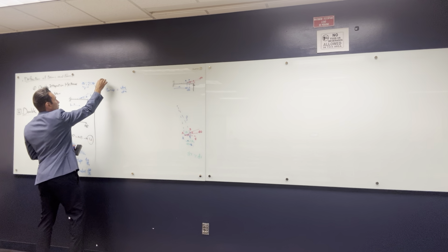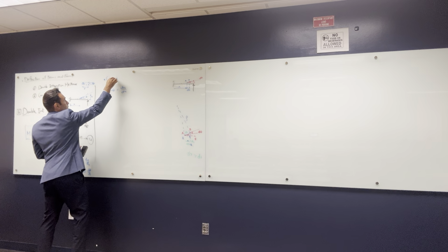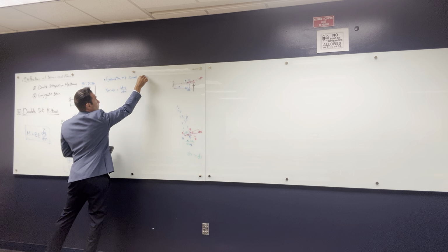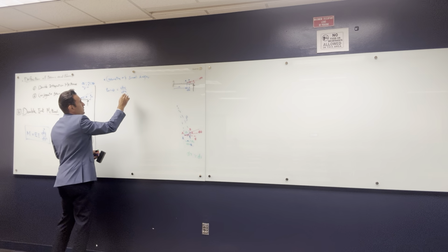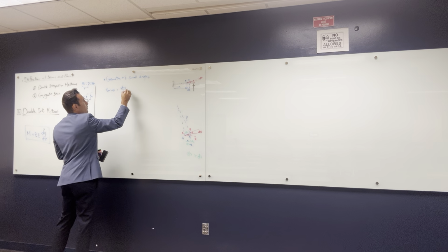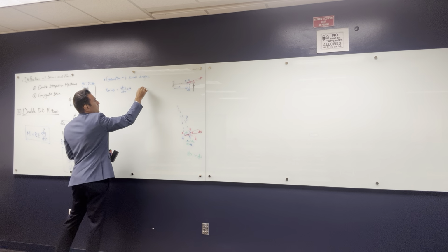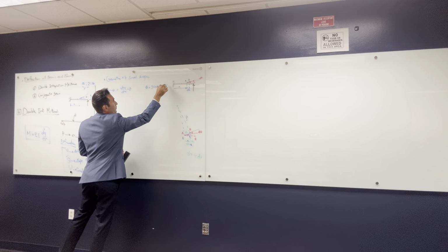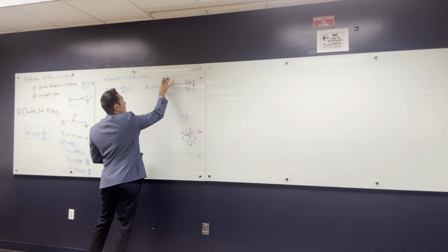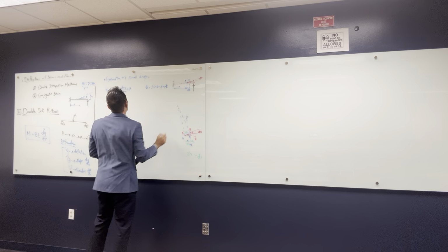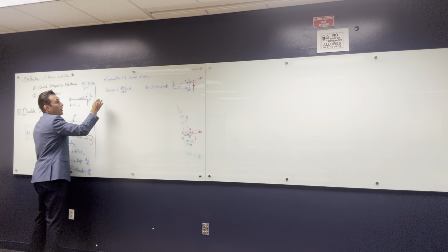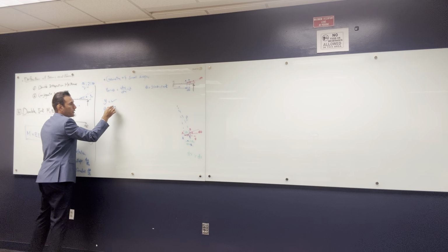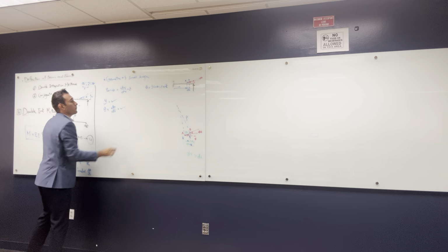And from the geometry of small angles, if theta is small, tan theta is equal to theta, also equal to sine theta. So right now, if I have y as a deflection and you want to get the slope theta, that's dy over dx. So I know that as well.